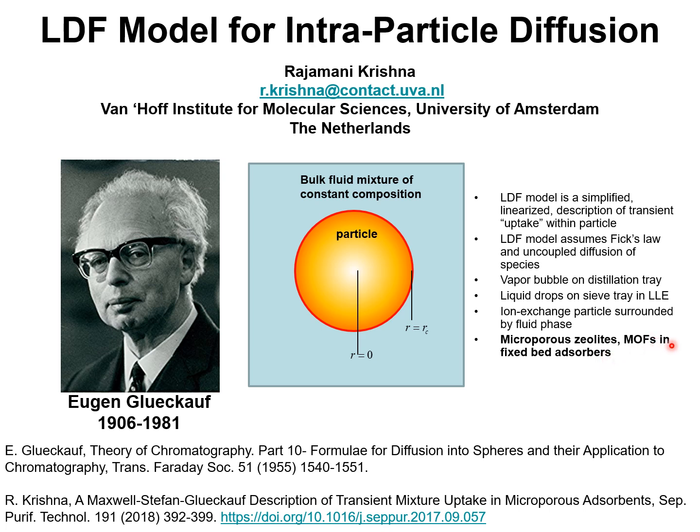Indeed, the focus of my presentation today is on application of the LDF model to describe mixture separations in fixed bed adsorbers. I also refer you to my own paper on the applicability of the LDF model for fixed bed adsorption separations, and this paper was published in Separation and Purification Technology in 2018.